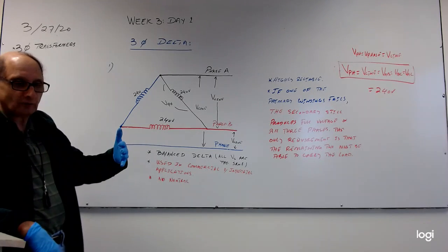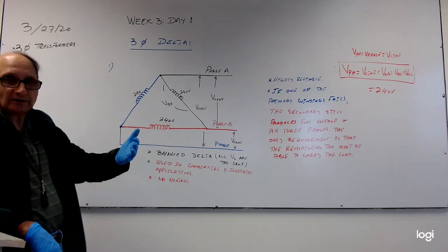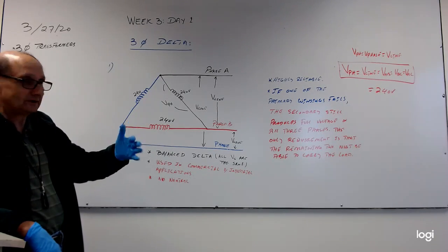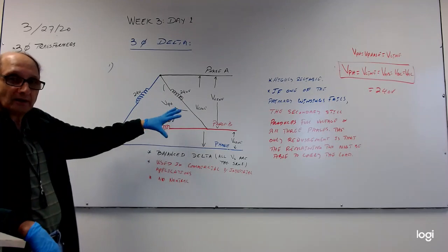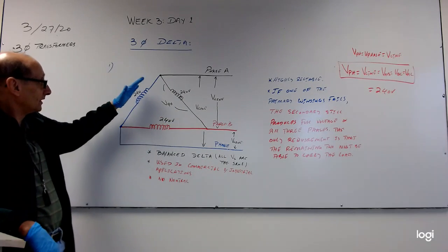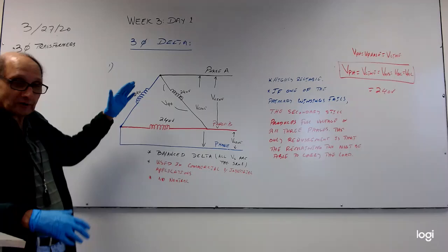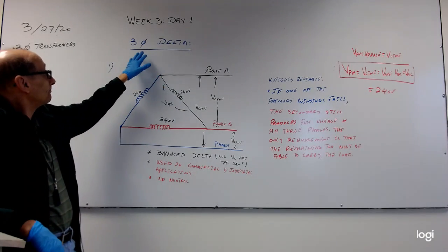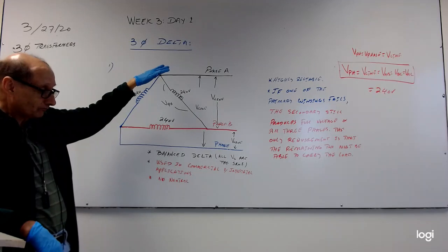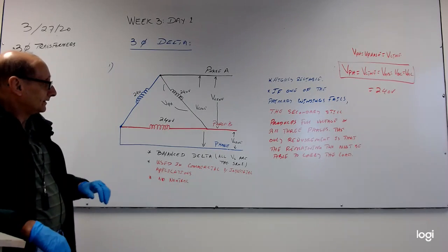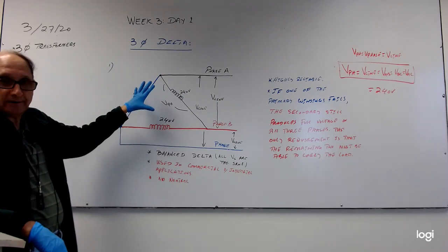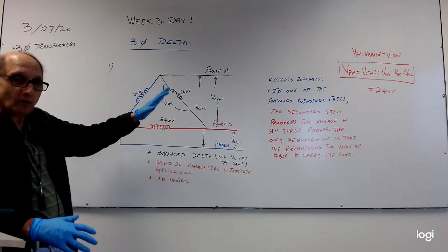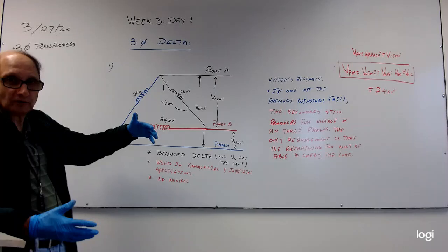Then I have 2 more items for another slide, delta high leg, and then star connection, because we can make some changes to this one. So we got a triangular shape configuration, also known as 3-phase delta config. This one does not contain a neutral, so we have 3-wire or 3-phase delta configuration.